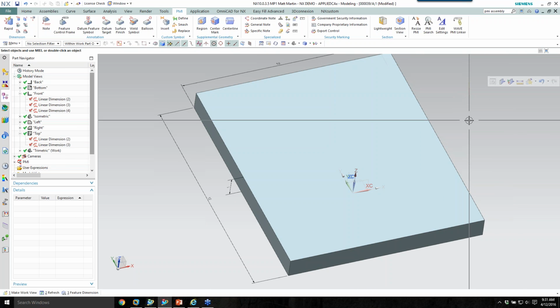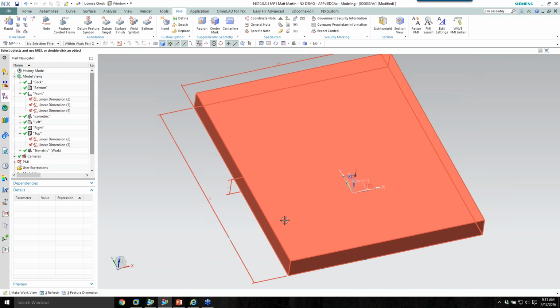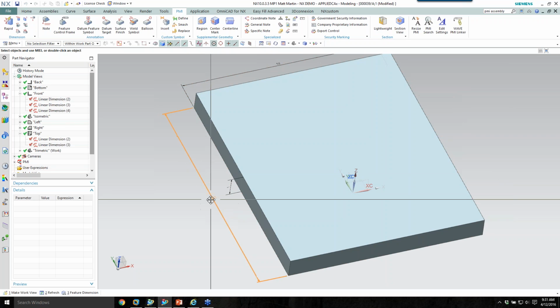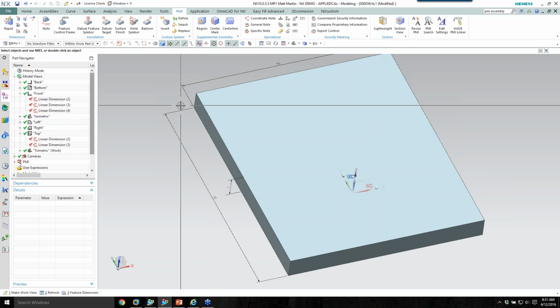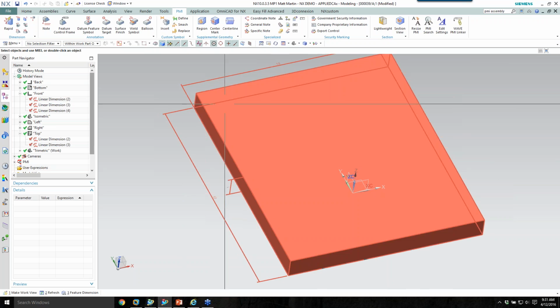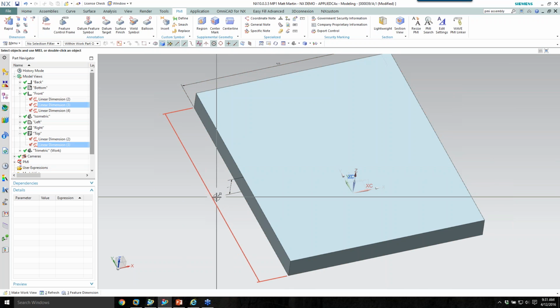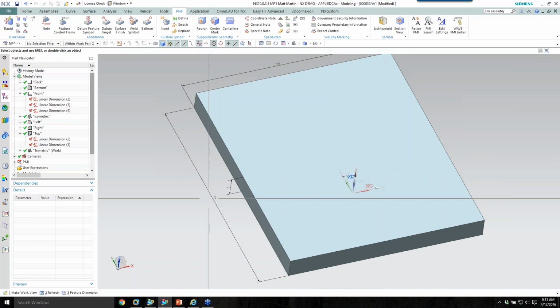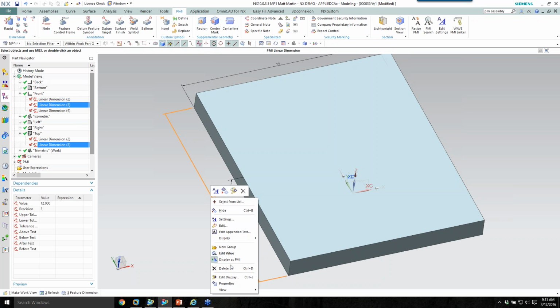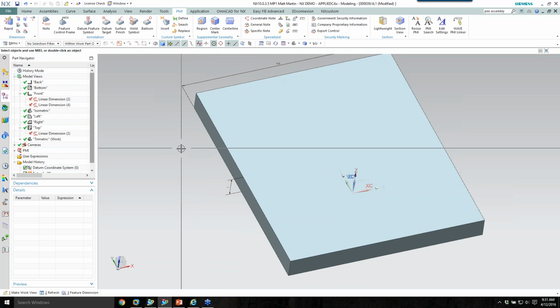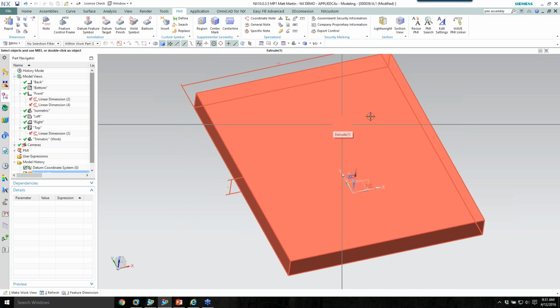So my approach now for moving forward in a PMI world is, if I can make a sketch and expose those entities as PMI, I'll do it. Sometimes I'm going to do some hacking away at this plate where this 12 inch dimension really doesn't apply anymore. So that may have to then be not displayed as PMI, and I'll put some other dimension on there as PMI.